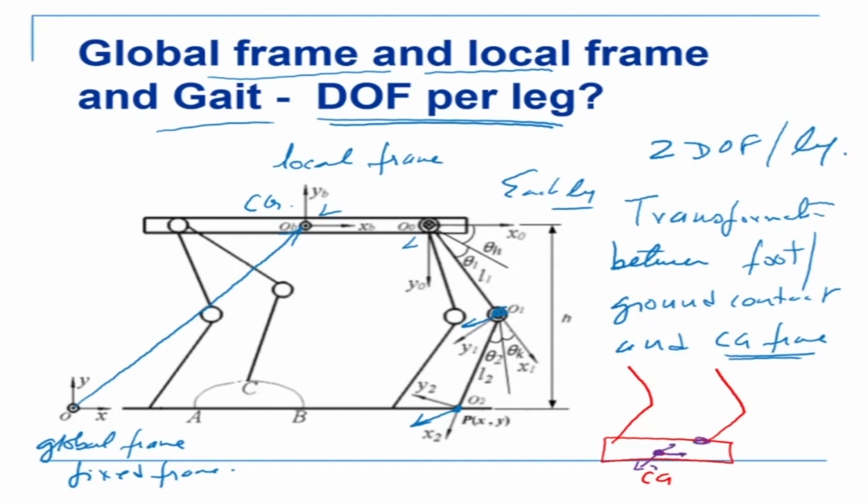Then this is 1 degree of freedom, this is another degree of freedom, and this is the contact point XY, we can say XYZ also. So each of these behaves like a serial manipulator, and now you know how to do the frame assignments and the kinematics. It is exactly similar to our serial arm manipulators, where each arm is equal to a manipulator. That is how we model this and do the kinematics.